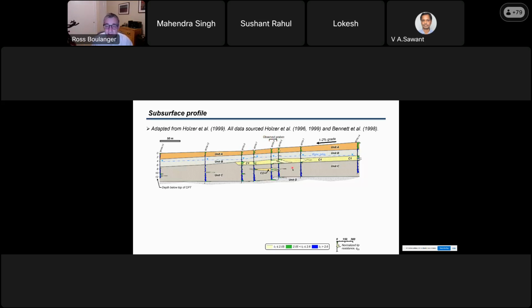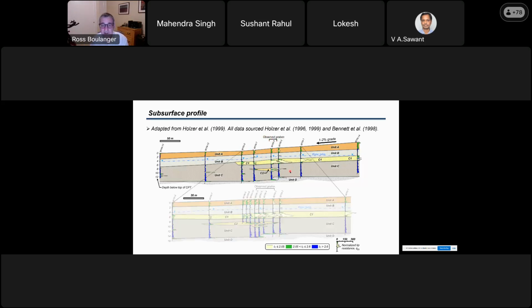Now, when we look at this model, they wanted to understand why the graben was there. So in this zone, they did a very dense array of additional CPTs. And if you took these individual CPTs close, you see lots of yellow, which from the CPT maps to clean sands. And then down here, it turns to a lot of green, which maps to silty sands. And there's a significant difference: these are looser, siltier materials, and these are cleaner, denser materials. That happens right about here.